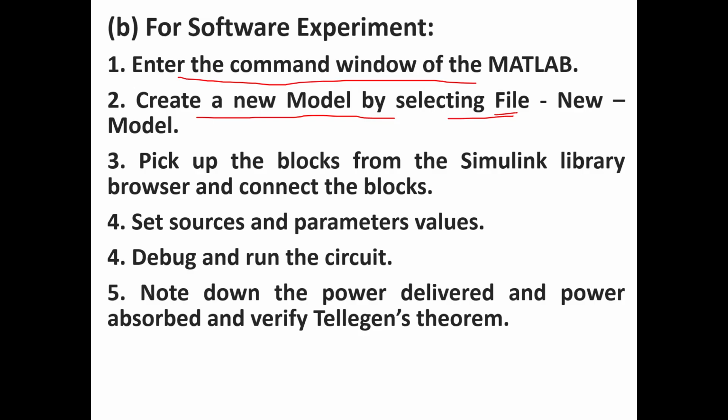Click with the left button of your mouse on File when you open MATLAB, then click on New, and later click on Model. Now an untitled page will open. Also open the Simulink library. Now pick up the blocks from the Simulink library browser and connect the blocks.